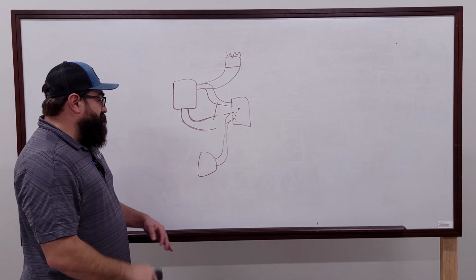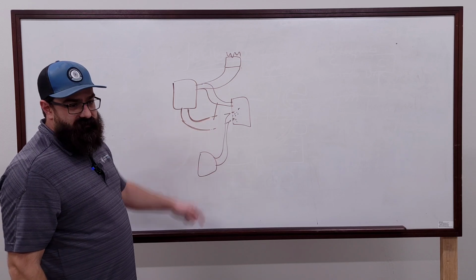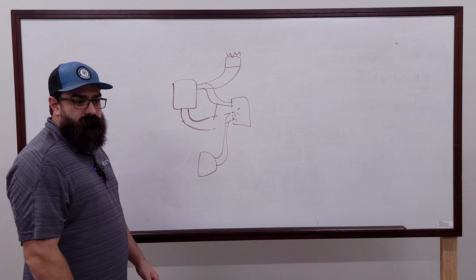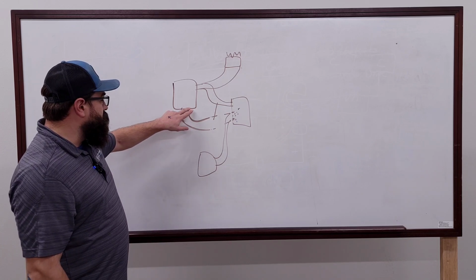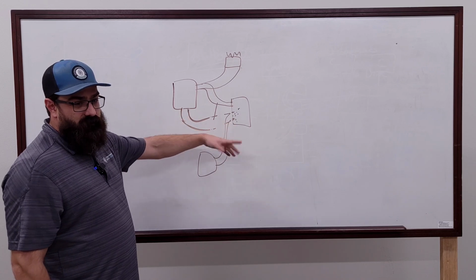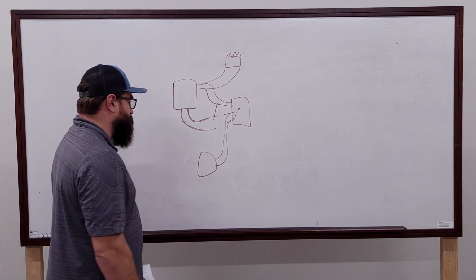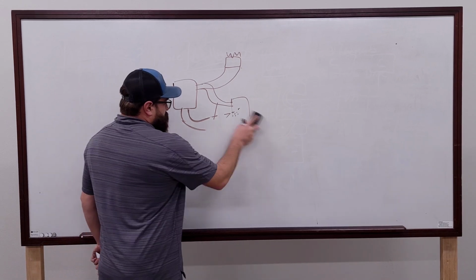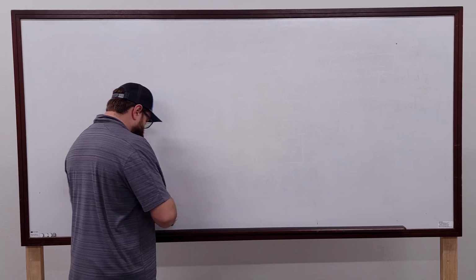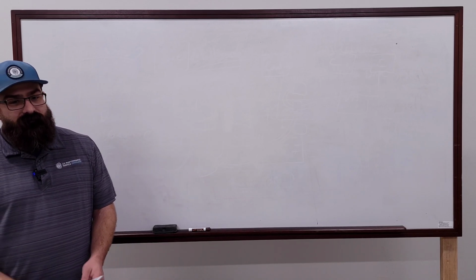I mean, it could be as simple as these two wires could be touching inside the jacket. Somebody could have pinched them and they could be touching. So you take it here before that short and it reads voltage. You come after the short and it doesn't. So it just depends. There's so many variables, just completely variable.